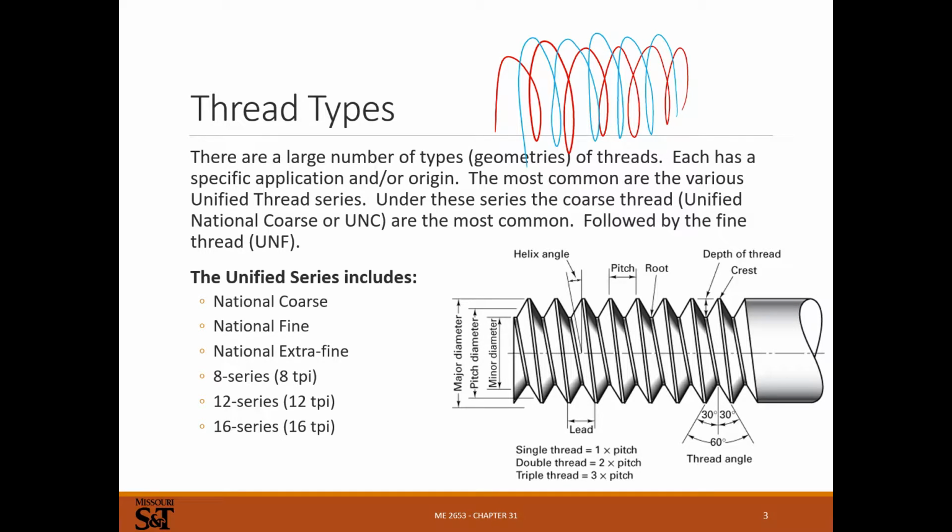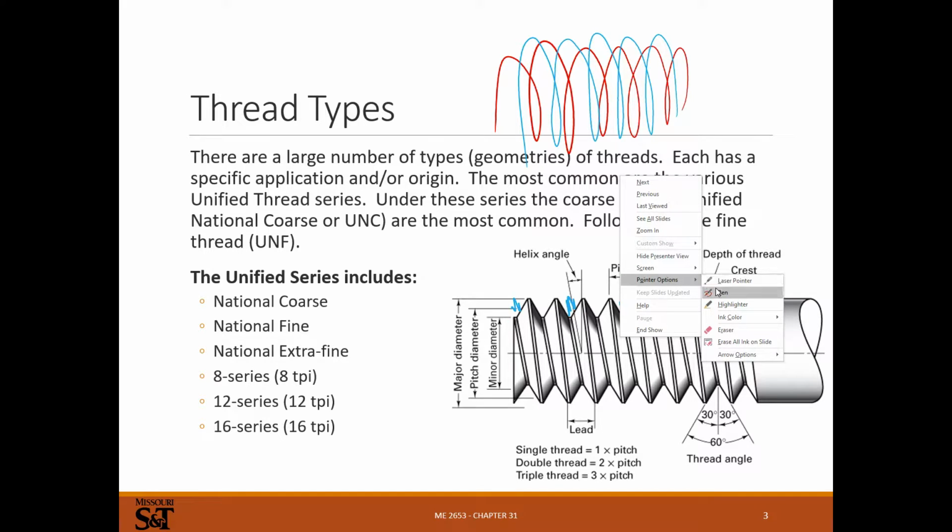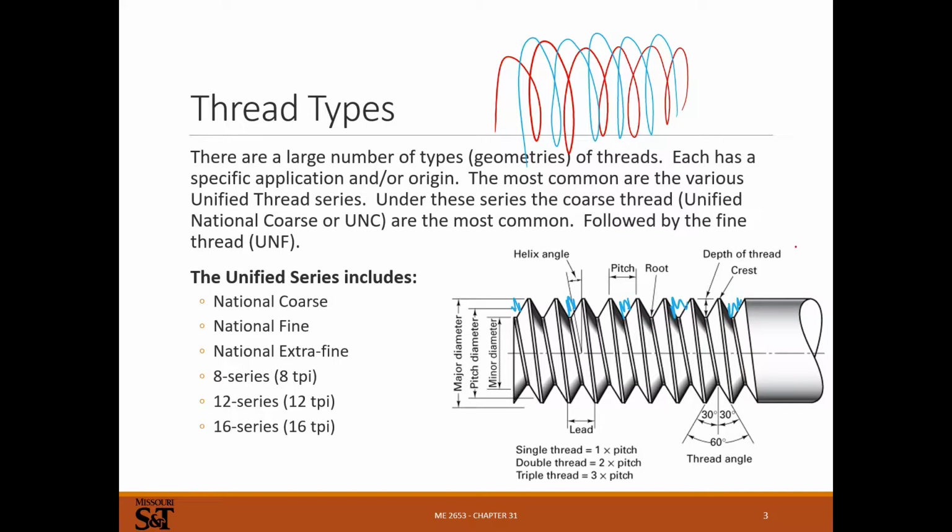And so those things would have to have a lot lower pitch because essentially, like one lead would be here, here, here, and here, and here. And then the other lead would be here, here, here, here. So in this case, the lead would be twice. So the pitch would be twice.